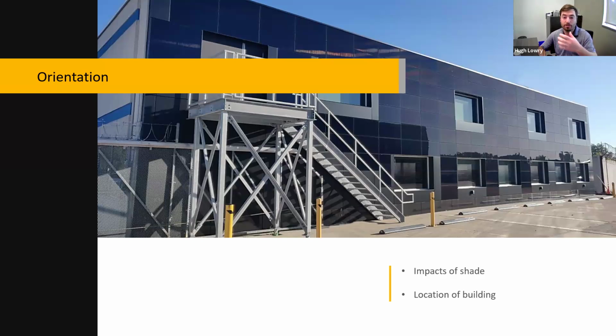Another thing that's mentioned with orientation is that typically you would want your solar panel to be entirely perpendicular to the sun rays for maximum generation. So in the northern hemisphere, that's somewhere around 30 degrees tilt. But we're obviously stuck with a 90-degree tilt because we're trying to apply our solution to facades. So that has to be a consideration as well.